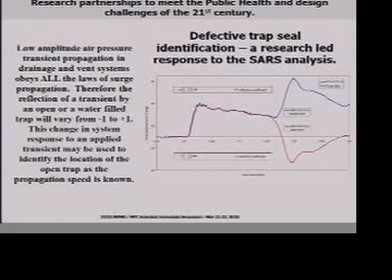Because if you generate a pressure transient in a duct and you measure it round about here, you will get a positive pressure wave as that transient goes past. What happens next depends on the terminal condition. If the terminal condition is closed, you get a positive reflection of that transient, as we see here. If the end is open, you get a negative reflection.